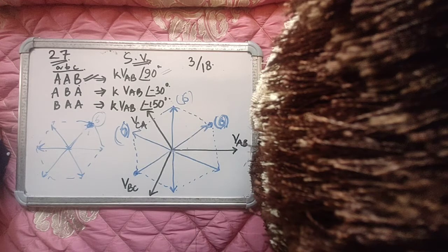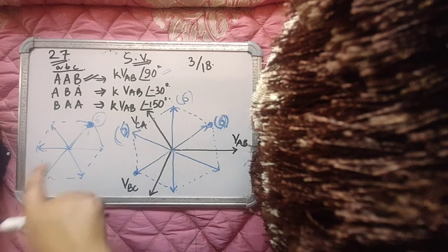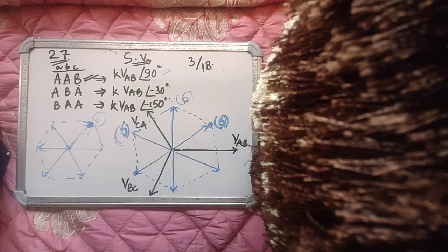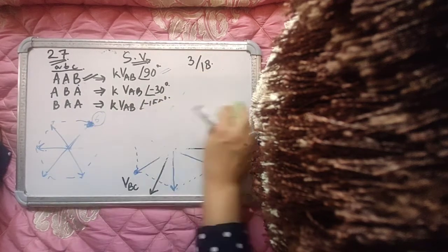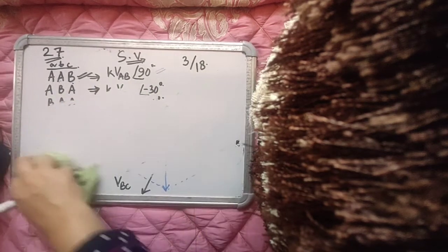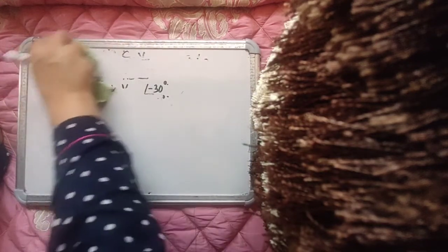My basic point is that in matrix converters, because you have redundancy associated with each space vector position, we use that redundancy to control source currents as well as load voltages simultaneously. So that was about the space vector implementation of the matrix converter.